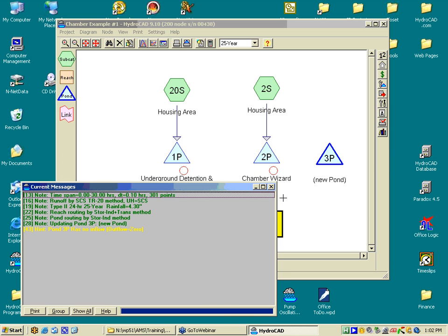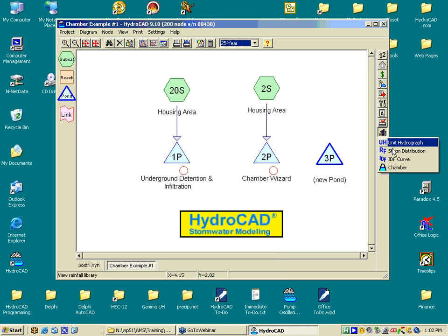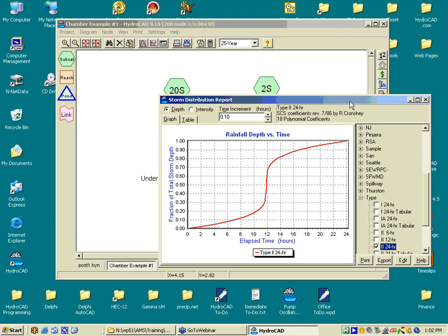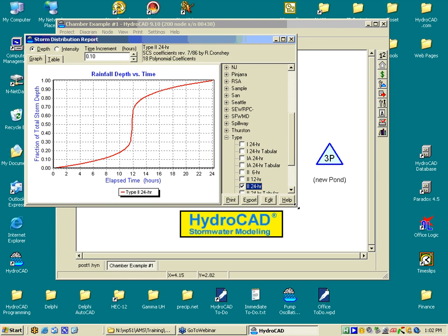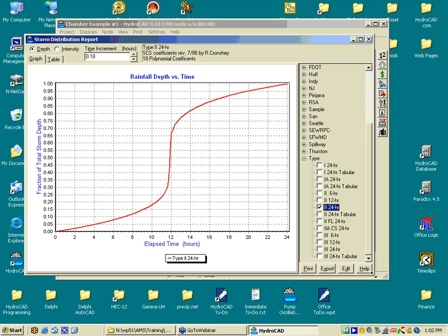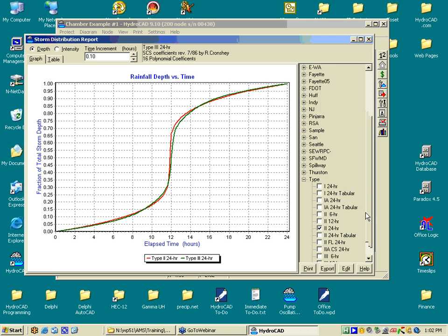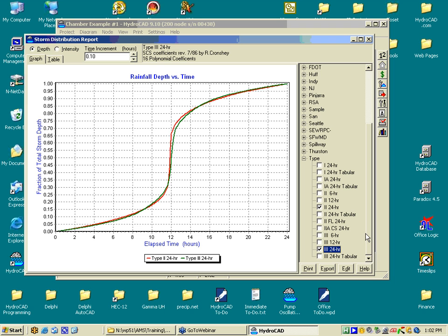I do know that we have, under the network pull down, under sewer network libraries, the ability to define 7 different types of rainfall events, not all of which apply to this SCS pond sizing, but we have the TP40, which was, I believe, the method we were using. We have the Hydro 35, and of course we have IDF curves, rainfall intensity charts that you can enter, and so we have a variety of methods of entry, but I'd have to defer really to Shan on that question.